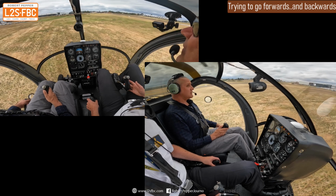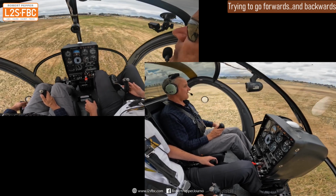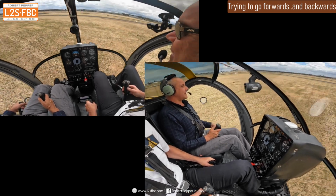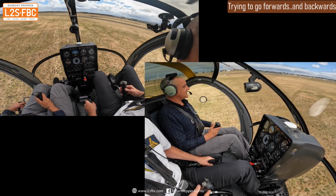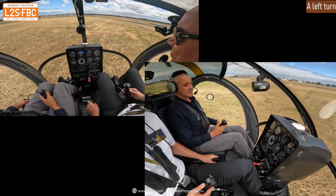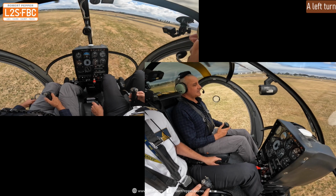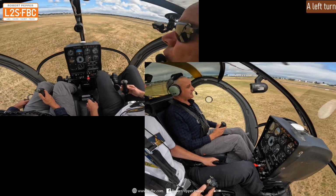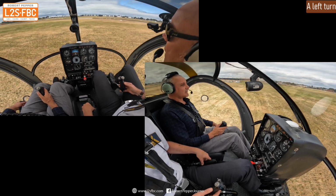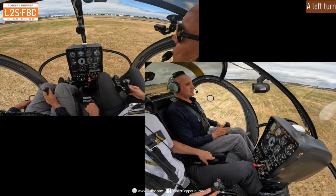Okay, now I'm going to try a turn whilst hovering, which is really difficult because part way around the turn the wind is pushing you, then it's against you, and that means you've got to change the amount of rudder, which also changes with the throttle and with the collective. And then you've basically got to keep the rotor blade tilted into wind as you rotate around it.